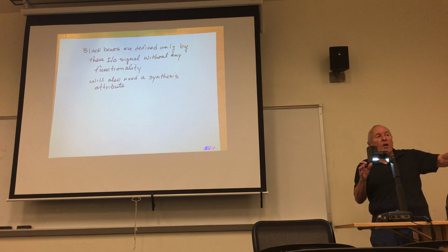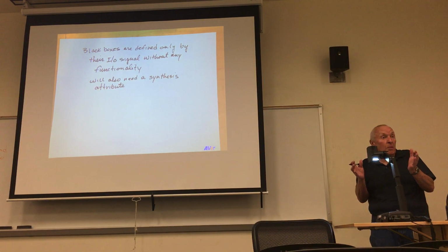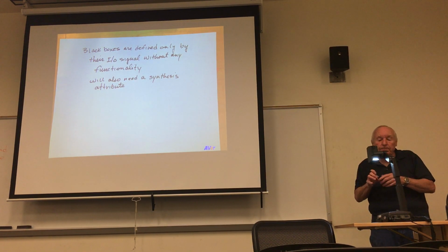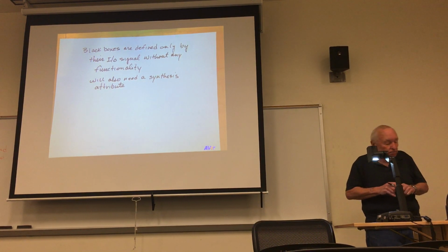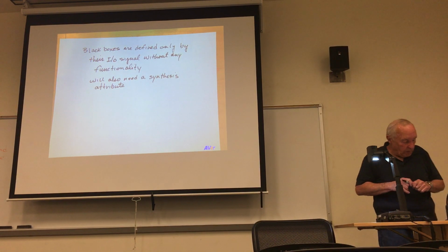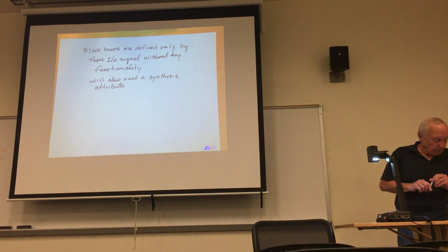I'll tell the place and route what the netlist is. I will tell you the signals that would go into this module and come out of this module. But just leave a space in the netlist for that to be plugged in. So you're gonna need this synthesis attribute as well.